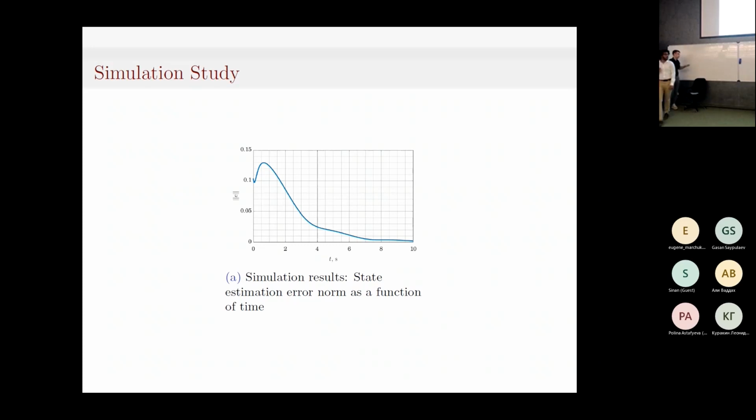It was just containing zeros and ones. And the initial error was like 0.03. And we also assumed some initial parameters like stiffness, etc. We applied this to the formula for the Luenberger observer and obtained this result. Also, we've used the norm formula, which I guess is straightforward.